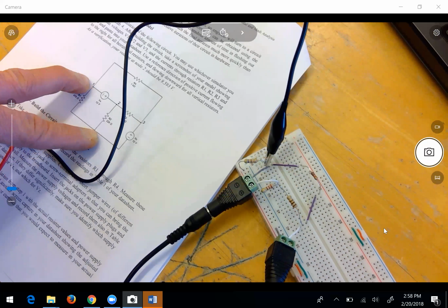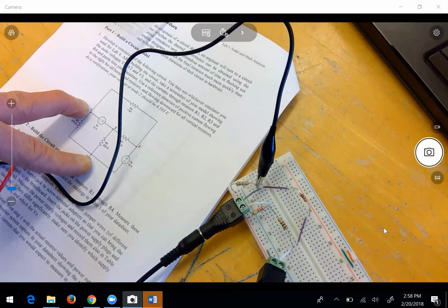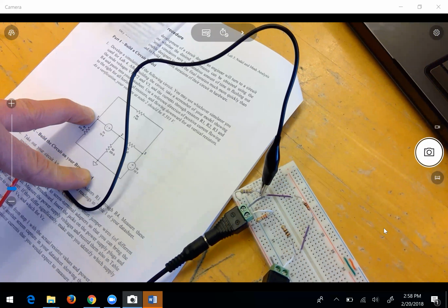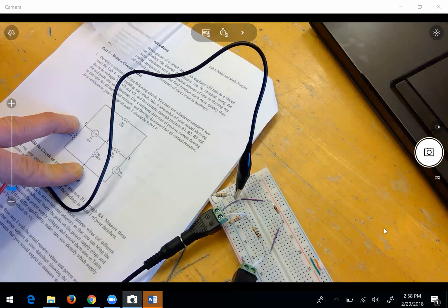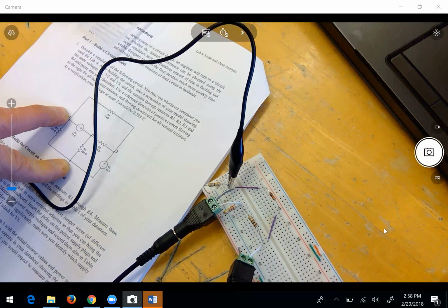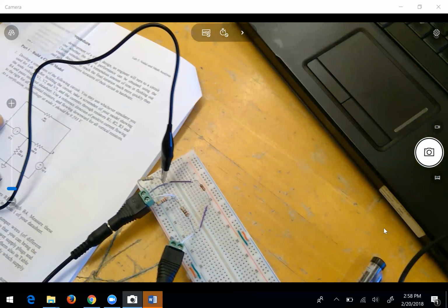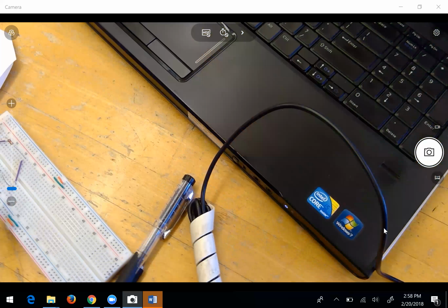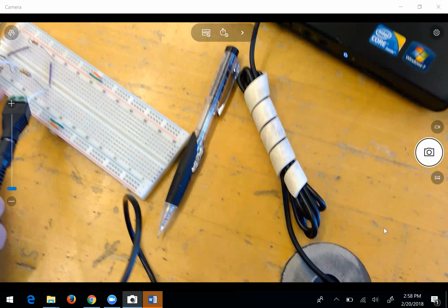Well, where do you click ground into? Well, what does ground mean? 0. So which node is considered 0? Off the breadboard. No. According to my fingers, which finger, my middle finger or my index finger, is connected to ground? Your index finger is connected to ground. You're right. Yeah, but that's where the common wire goes for your voltmeter. But where is that? Well, on your circuit, you have a reference node. You built this thing, right? Don't you have the correspondence between this part on your schematic and your breadboard? Can you point to me where that is? Should you have that figured out?